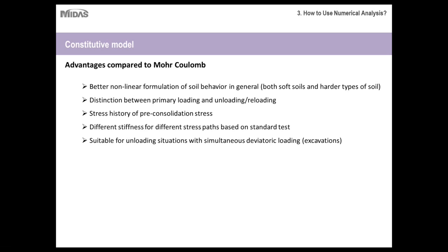They are also suitable for unloading situations with simultaneous deviatoric loading, which is the definition of excavation in terms of numerical analysis. Unloading means that you are excavating your earth mass, and as and when you excavate, you are developing deviatoric loading onto the structure due to the unloading.